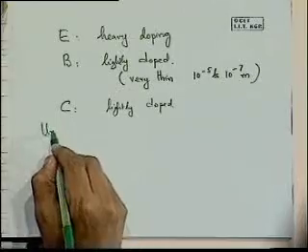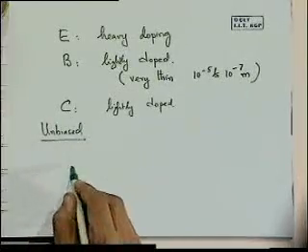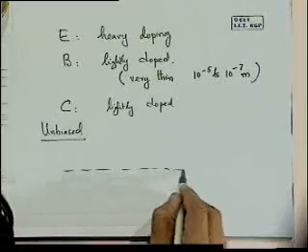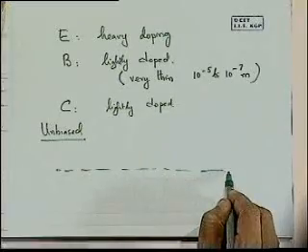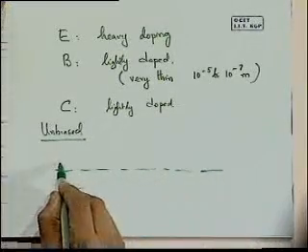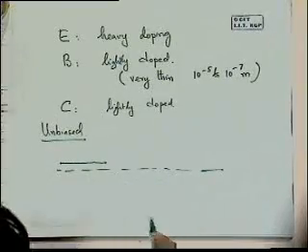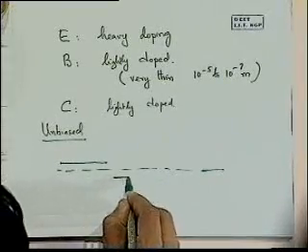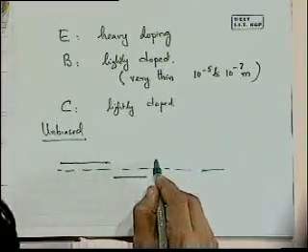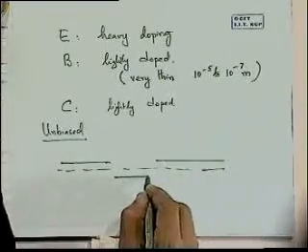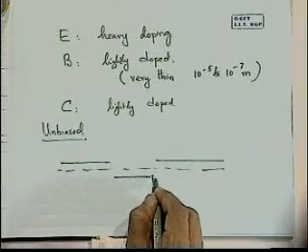Now we'll consider what the band picture looks like in the unbiased case. And as before, we start off, given that it's unbiased and everything is in equilibrium, the Fermi level is the same throughout. On the left, we had an N-type material, so we are close to the Fermi level there. In the middle, we have a P-type material, and then again you have N-type material. So in P-type material, this is my valence band, right?